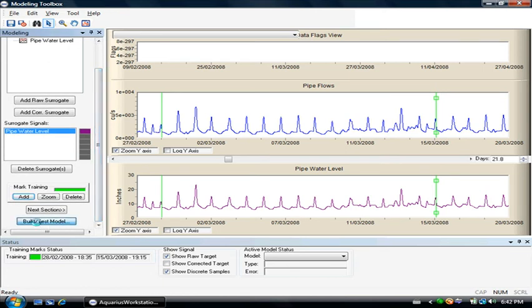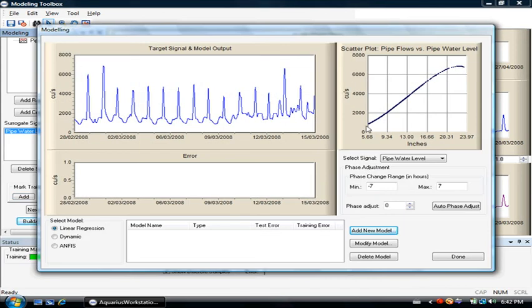So if we choose to build or test a model in that particular section of data, it's going to grab that data. And you can see right there the relationship between the depth of water in inches and the cubic inches per second, the flow. And you can see that exact topping off as our pipe starts to get nearly over full. We get a flattening of the relationship as the roof of the pipe, the roughness on the roof of the pipe, starts to restrict our flow.